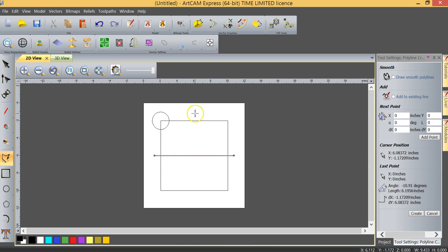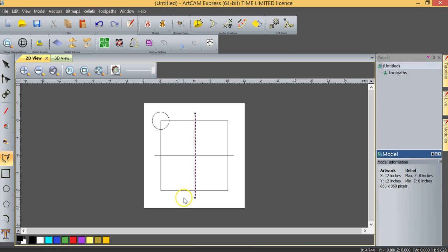I'm going to do exactly the same thing on the vertical plane this time. So my start point at the top, left click, release the left mouse button. Come down to the bottom, find my vertical plane. It does the same thing as it does in the horizontal plane. Left click to set my next point. Right click to complete the operation, and center.